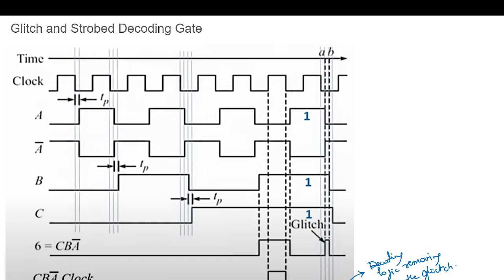In this counter, if we have some propagation delay, at this negative edge we observed the toggling, but now it is toggling after a certain propagation delay here. In a similar way it will be at this edge. So here it was toggling after one time delay. Now here also there is a shift of the edge; this is the clock edge.